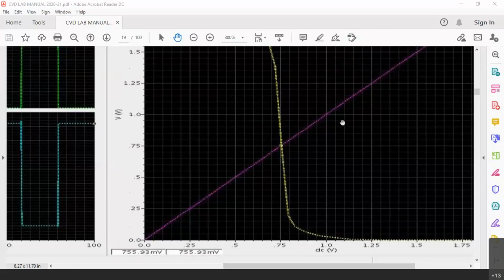I don't know, sir. I should guess only. Okay, fine. But do you remember the drain current equation of the MOSFET? Yes, sir. IDS equals mu n into Cox into W by L into (VGS minus VT) whole squared by 2. That is one equation, right? So drain current equals mu n into Cox into W by L into (VGS minus VT) whole square by 2.